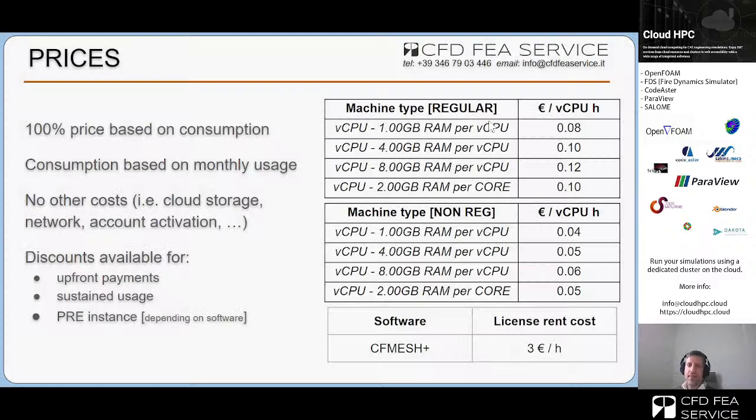All right, as I was saying before, let's have a quick overview of the costs of the cloud. Keep in mind that every simulation, every single mesh and CFD simulation, used roughly 20 virtual CPU hours. So we performed 6 simulations, so we used 120 CPU hours to compute these 6 geometries, 6 meshes.